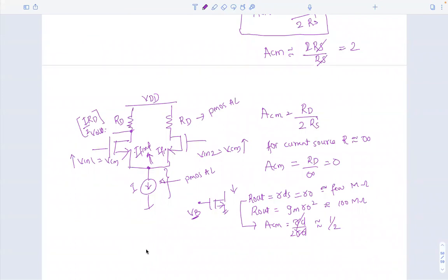See, one more way of doing the interpretation here is, so you have an NMOS. So again, this is a current mirror. Okay. So here, this node voltage is connected to here. Okay. So this node voltage is changing. Okay. So you have a curve. So this is ID and VDS. So basically, we are changing the points here at this point and at this point. Okay. So if this is more flat, something like this, then Rout will be higher.